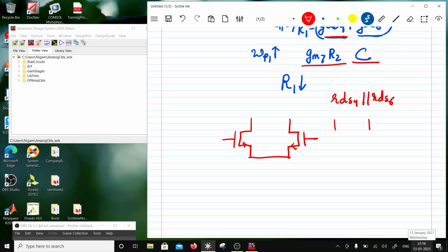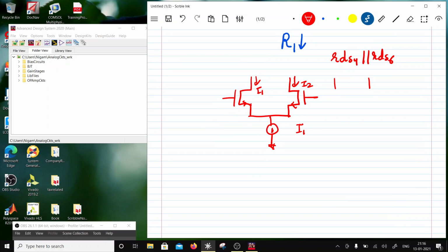So let's say this is my gain differential stage, and I use a load here and split that, so I have a cascode load. If I can split the load into two, and this current swing, if this is I1 I2, then the swing I1 minus I2 I am going to mirror out to another I1 I2, the other differential pair.